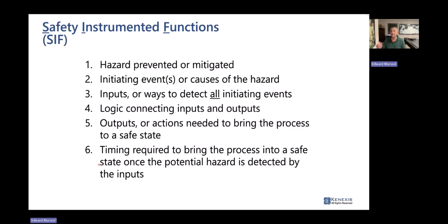So that's a big issue that we really need to address, and that's a problem that a lot of designers have in achieving their SIL targets because they over-specify what their outputs actually are. All we're looking for is a minimum and sufficient set of actions to bring the process to a safe state with respect to the hazard that this safety instrumented function is intended to protect against.